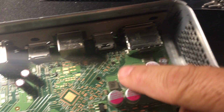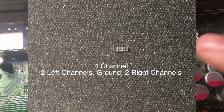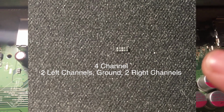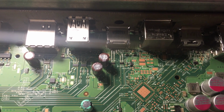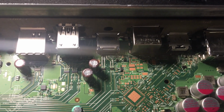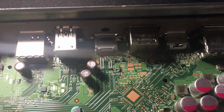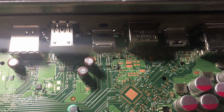Okay, so the only other thing to mention, Andrew Paul tests these things, but the basic thing to know is that there are 4 channels, and I'll show you in the picture where the channels are. Basically, there are 2 left side channels, a center ground, and 2 right side channels. And the channels themselves should be independent of each other. When you do a continuity test, if you see continuity between any of the channels, then it's a bad filter. Top and bottom straight through should have continuity, and then the second channel top bottom. But you shouldn't have left and right. It's hard to explain, but